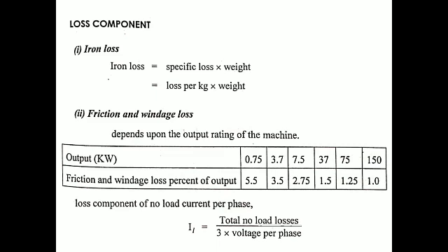That's all for the operating characteristics. Here the operating characteristic is the determination of no load values, that is I naught. That I naught is calculated from two components: one is Im and the other one is IL. Im is the magnetizing current, which is calculated from the total mmf value.